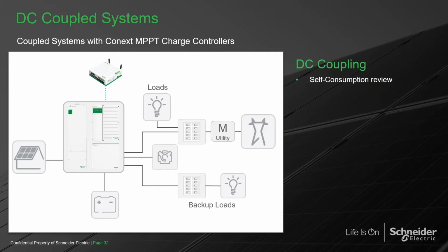So going back to my DC couple, this only works on DC couple, by the way. Going back to my example of DC couple, customer connected to the grid, whatever reason, he's not allowed to export power out to the grid. So what happens here? The power from the array goes out to the loads in the backup panel. Nothing to the main panel. So any load left here would have to be supported 100% with the grid. So the only loads that are going to get the renewable energy are here. Okay, so that's self-consumption up to now, what we could do today.